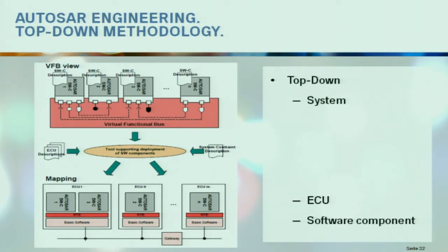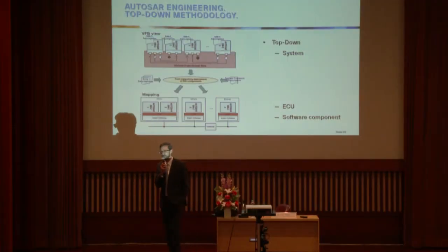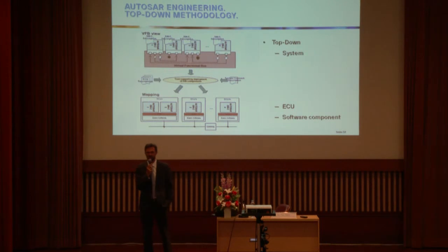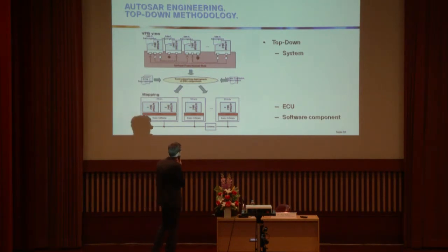So this is what we call the logical architecture. We're just interested in the fact that we have those software components and they communicate with each other. To realize this, AUTOSAR developed the concept of a virtual function bus, meaning this is not a physical bus, but a virtual bus, over which the functions communicate with each other. And this is the top-down or the system level.